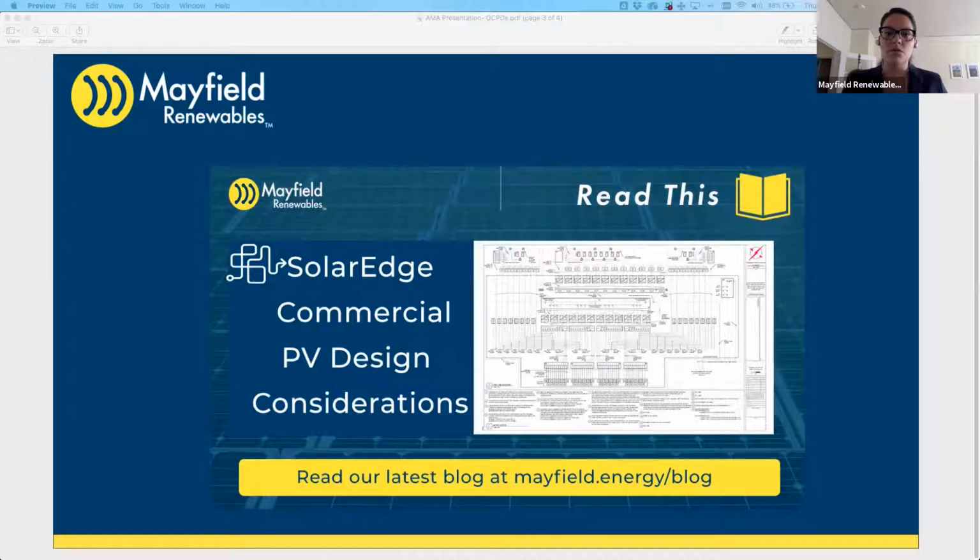NEC Table 250.122 covers equipment grounding, and it says that they are to be sized based on the rating of an OCPD in the circuit ahead of the equipment. So the question is, how does one determine the equipment grounding conductor size for circuits without an OCPD? They're specifically wondering about PV source and output circuits to unfused inverter input terminals. Is there an assumed OCPD rating based on the PV module max fuse rating?